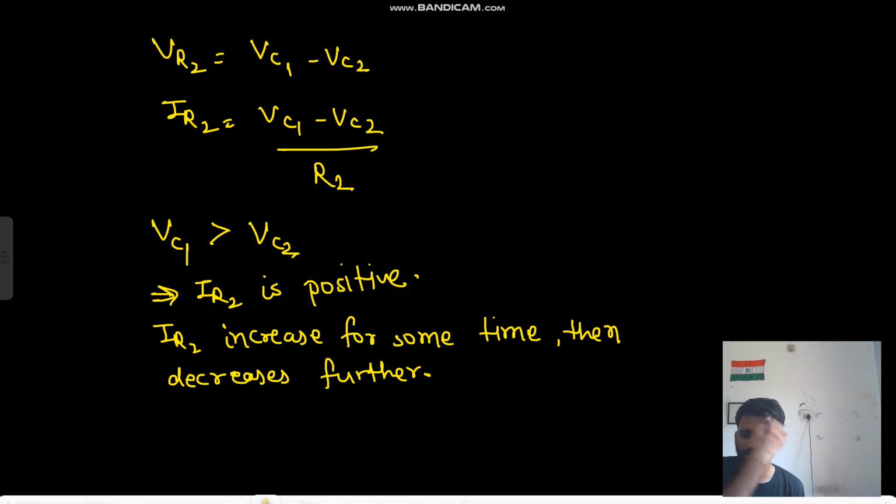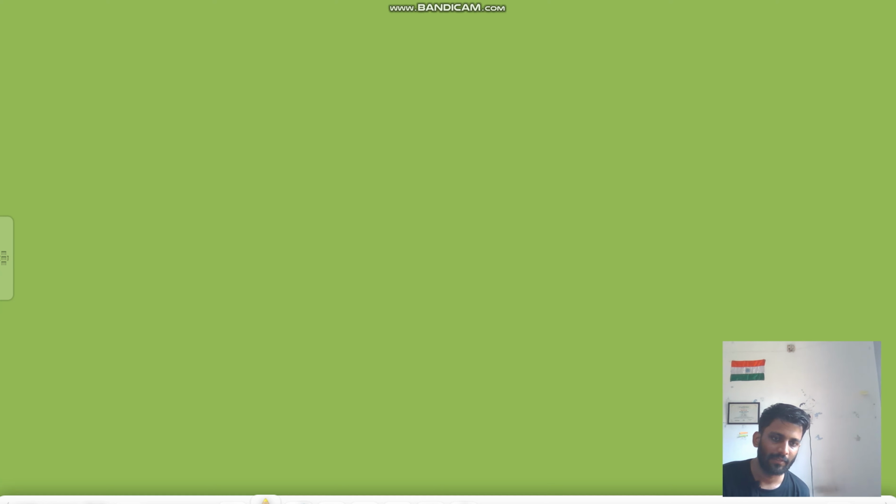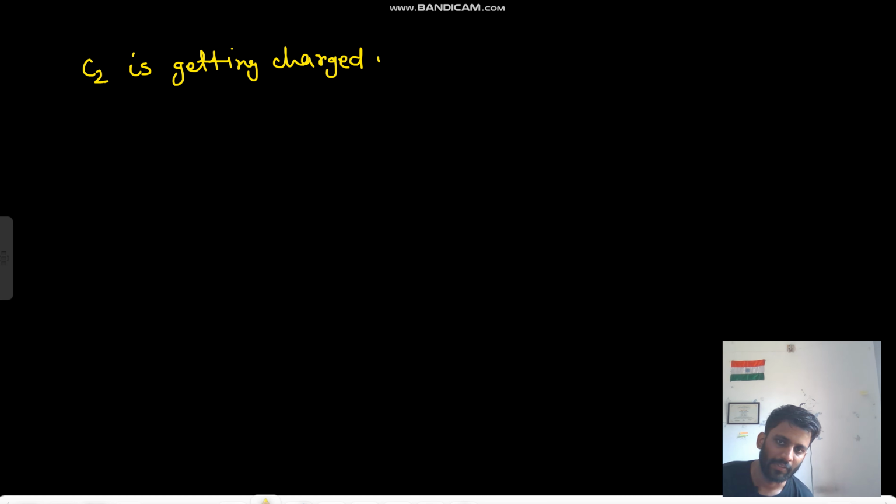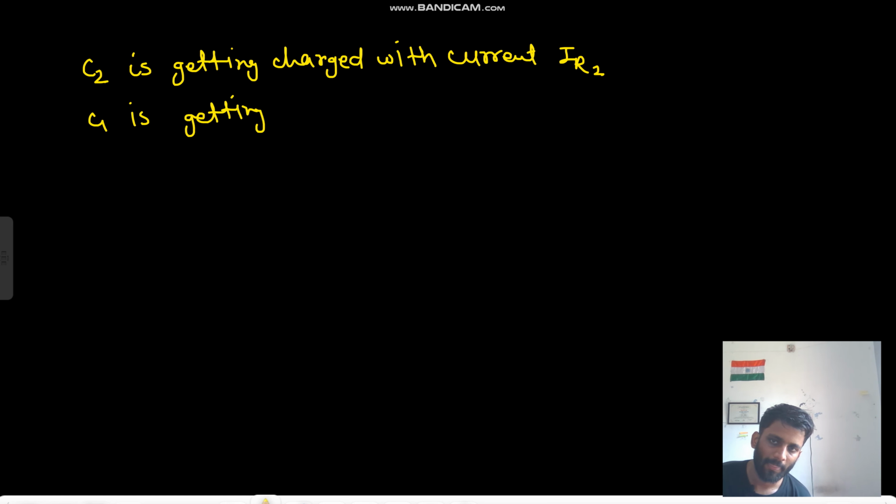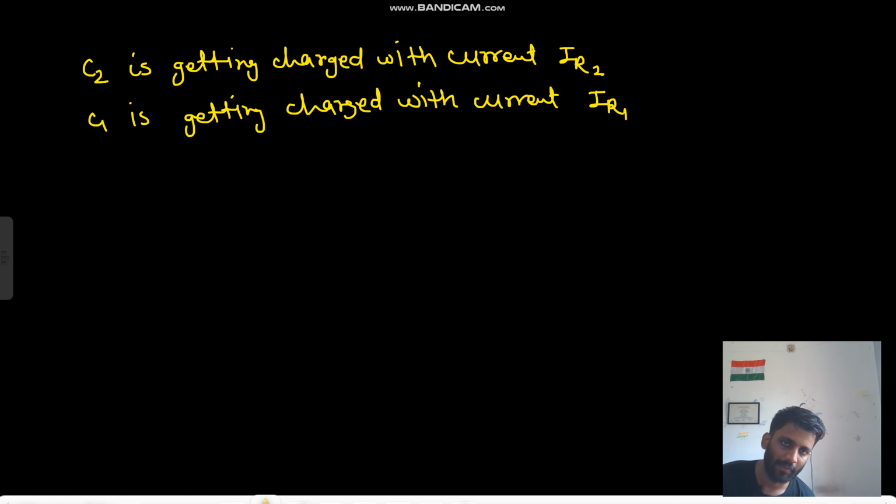Why so? Look, what is your IR2? Again I am writing, it is VC1 minus VC2 upon R2. C2 is getting charged with current IR2. C1 is getting charged with current IR1 minus IR2.